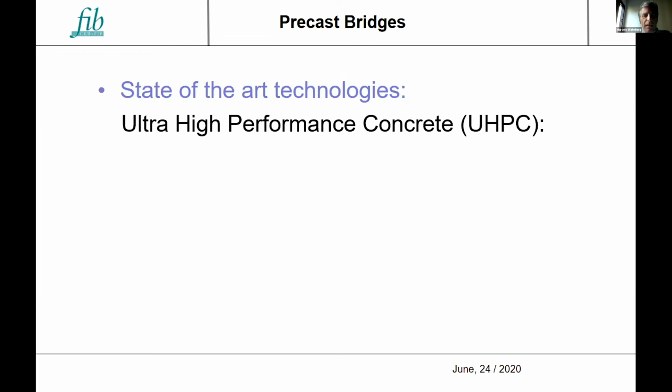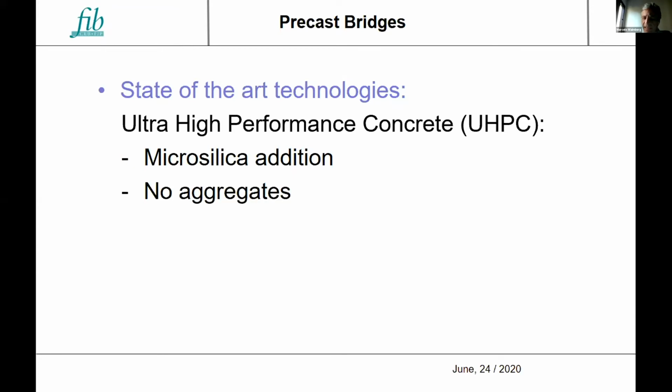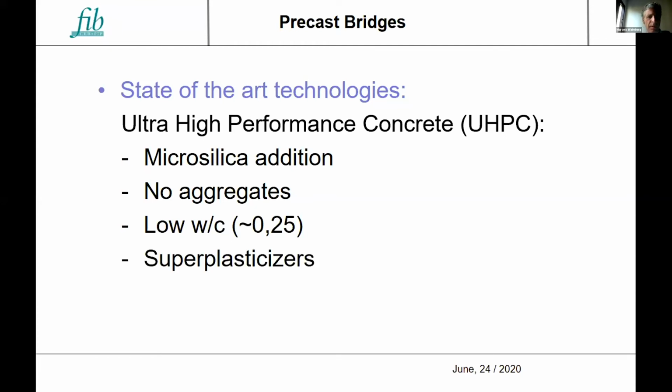And they are developing this document on the use of UHPC. We're talking about, as you've previously heard, a material with microsilica addition to that mixture, no aggregates, very low water cement ratio, the use of superplasticizers to make it feasible to use, and steel fiber addition.